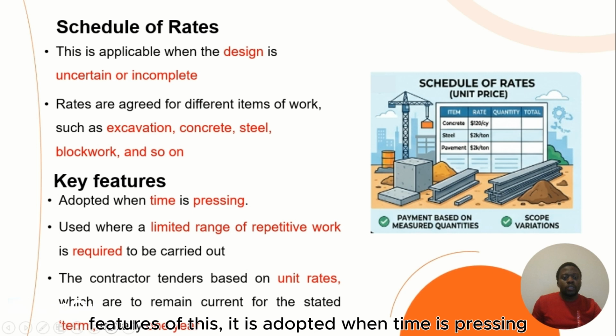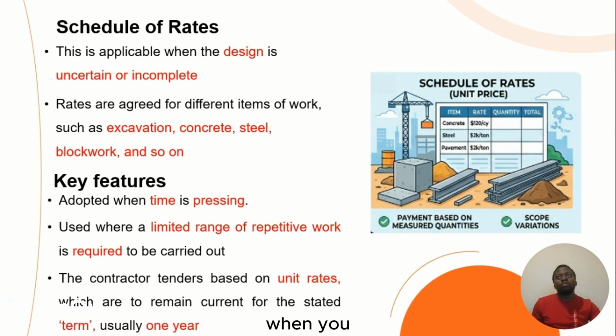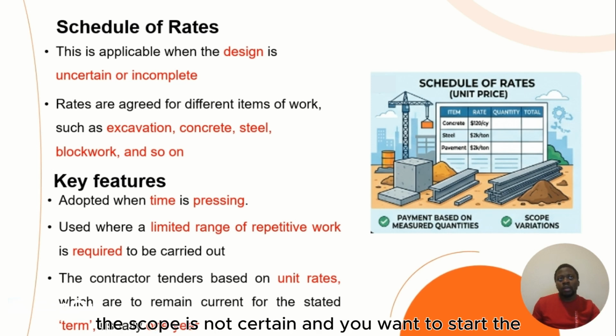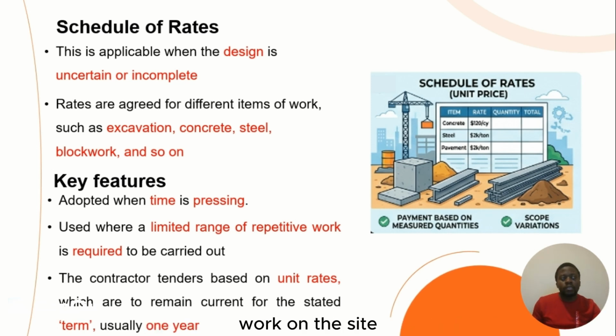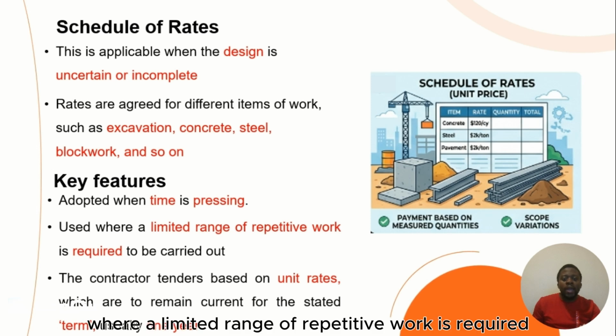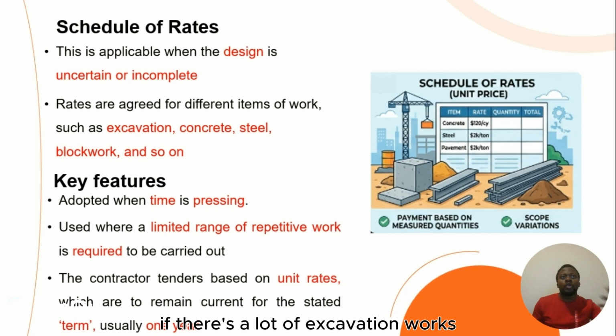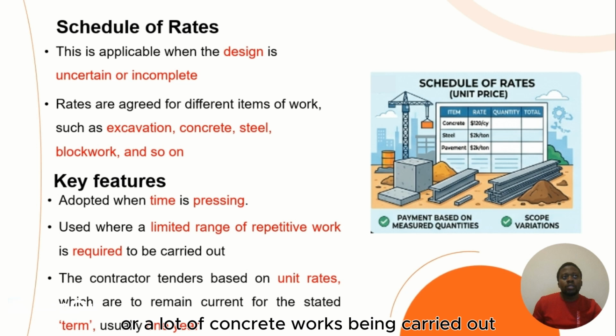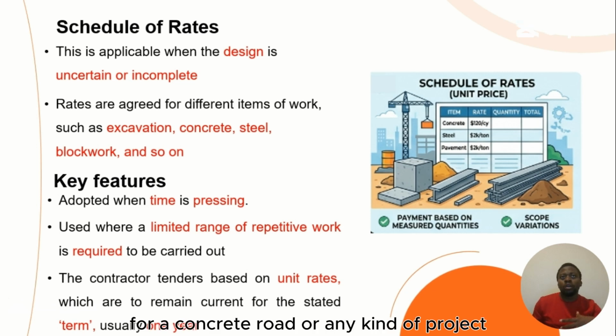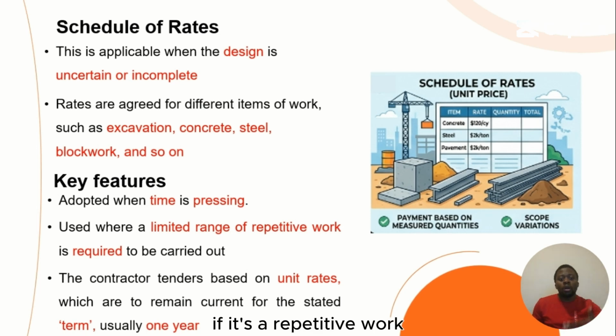One of the features is that it is adopted when time is pressing, when the scope is not certain and you want to start the work on site. It is used where a limited range of repetitive work is required. So there's a lot of excavation work, maybe for road construction, or a lot of concrete work being carried out for a concrete road or any kind of project. If it's repetitive work, there should be a standard rate that is agreed by both parties.